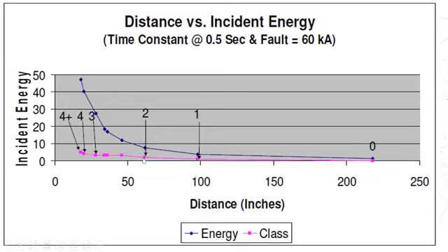But they approached closer, and the working distance was reduced from 36 to 24 inches. So at that particular location, now the incident energy will be around 30 cal per centimeter square.